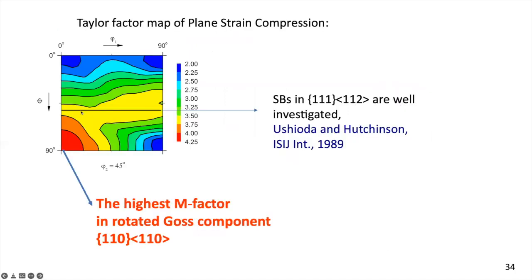It is well known that shear bands appear in grains with a higher Taylor factor. The reason is energetic: these grains have an energetic advantage by concentrating the shear, spreading the plastic deformation over a very small zone of the volume of the grain.